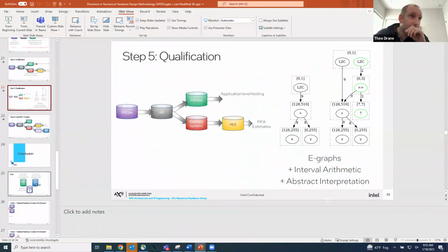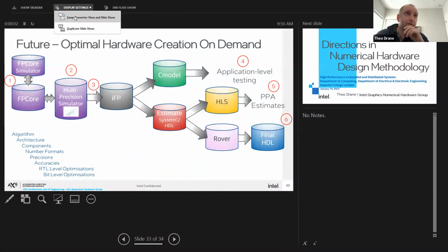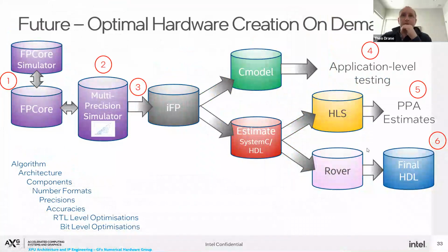So this allows us some progress. There's the start of formal verification for this. We have a formal verification story for this. If it is done manually, then formal equivalence checking between optimized HDL and your behavioral HDL, whatever it is, that's a manual exercise, but that's quite routine in the industry. So that's this piece of the puzzle.